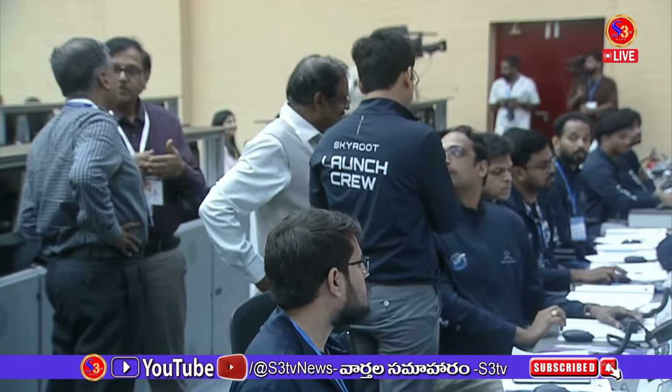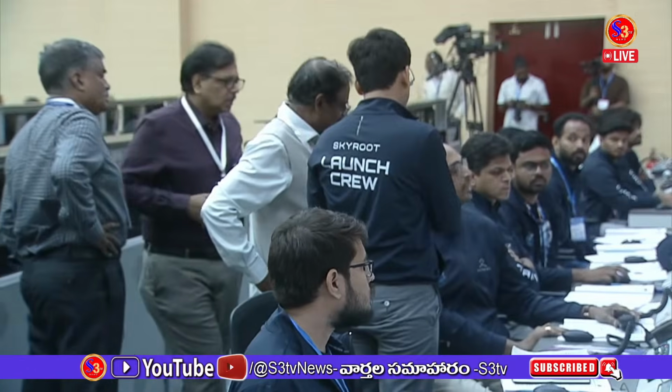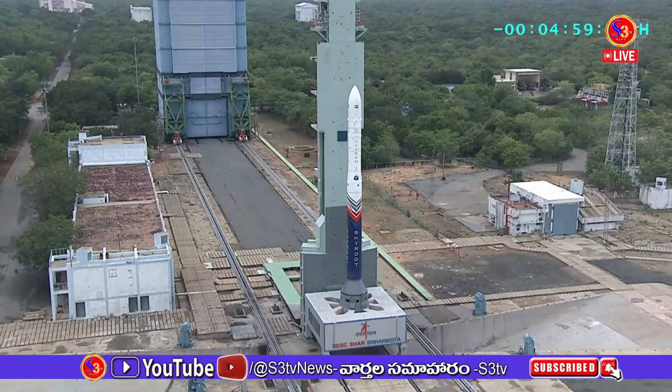And one thing that's always curious is, why is the rocket heating up while it's going up in the atmosphere? Right. So as we are accelerating into the dense atmosphere of Earth with velocities almost 3 to 4 times that of sound, the air in front of the vehicle rapidly gets compressed, and just outside the vehicle surface will have extremely high temperatures, which then get convected into the vehicle surface.